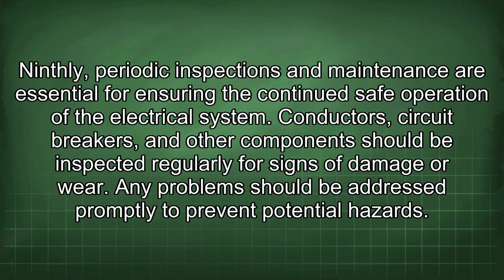Ninthly, periodic inspections and maintenance are essential for ensuring the continued safe operation of the electrical system. Conductors, circuit breakers, and other components should be inspected regularly for signs of damage or wear. Any problems should be addressed promptly to prevent potential hazards.